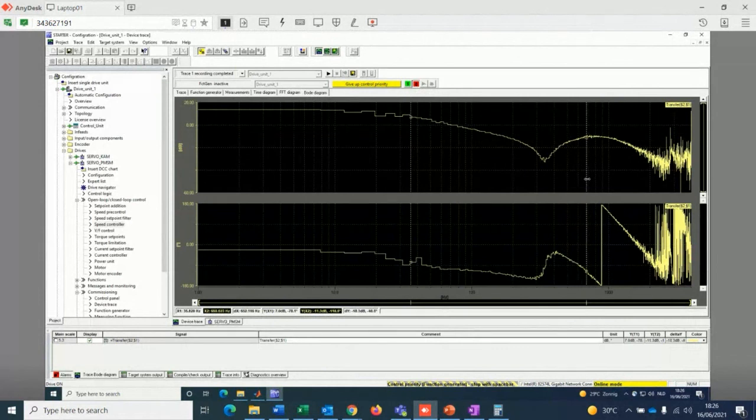So first we will check the amplitude margin. For that we go again to the point in which we find the jump on phase. So it's here. We see that for that point we have minus 10.2 decibels, which is lower than minus 10. So we are achieving that criteria. So we fulfill the first criterion.